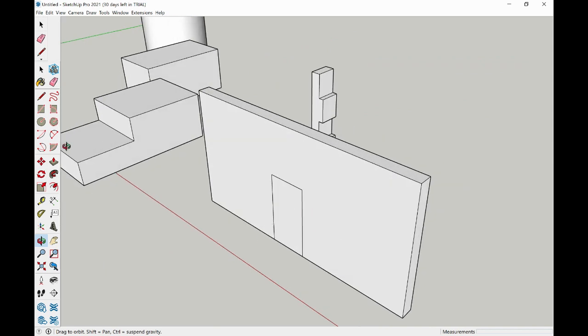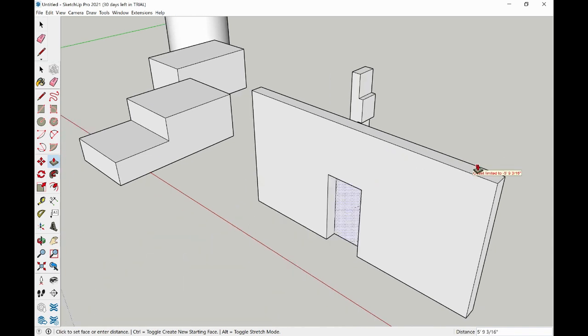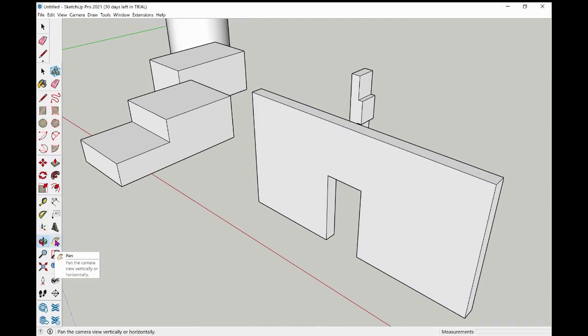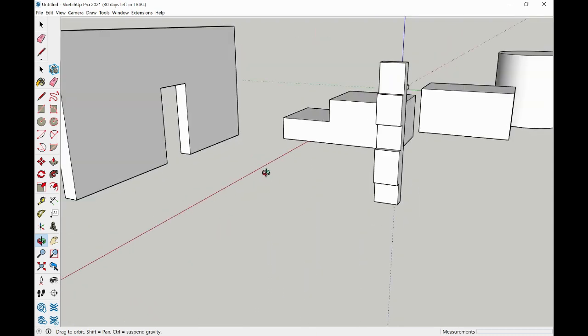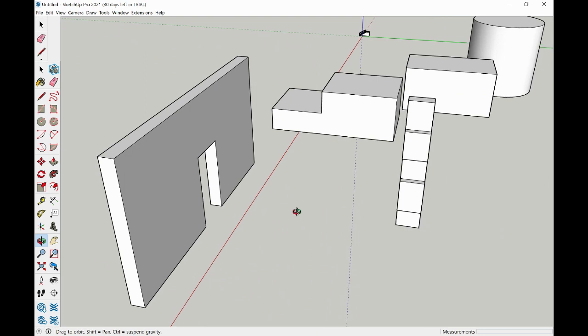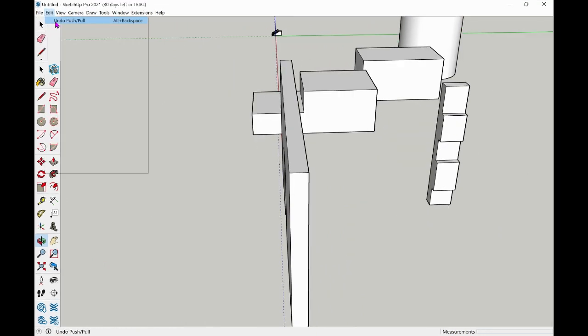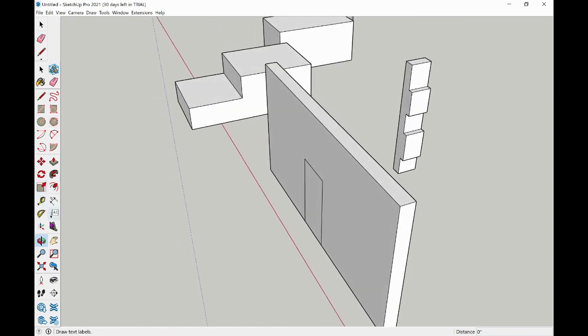What it's doing is making one surface join another surface. That other surface is the back of that wall. When I click, and I'll do that again, the back of that wall or that edge, I'm telling it to join it. And when it joins it, it disappears. I'm simply using my push-pull, moving it.